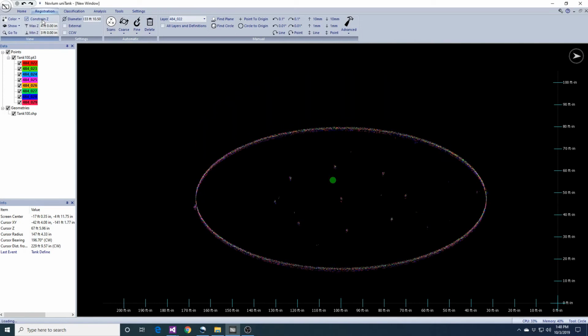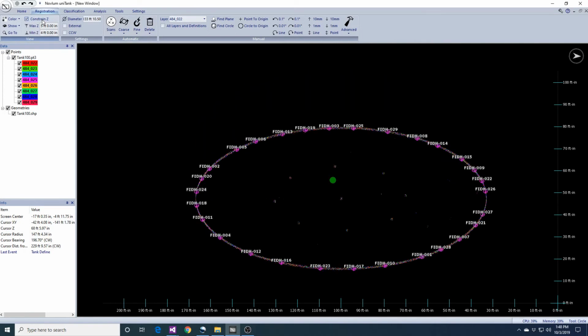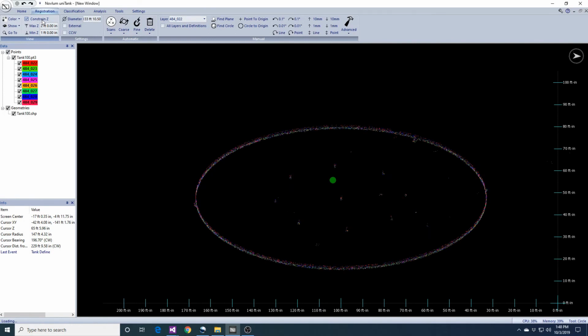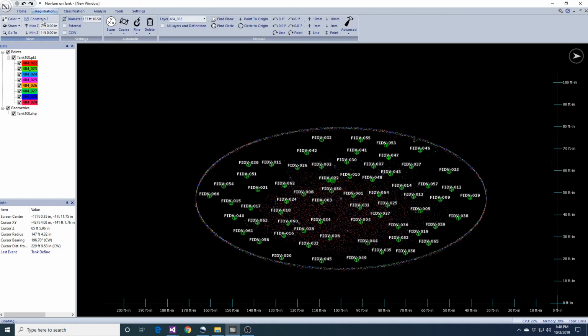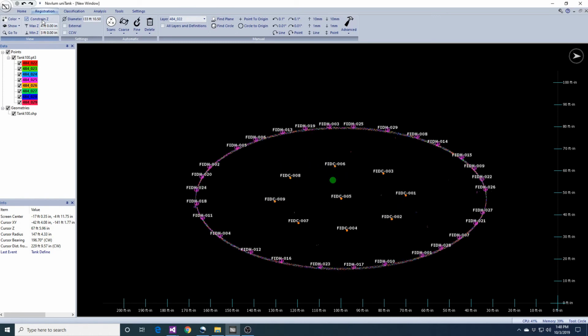The surface fiducials on the shell control horizontal translation. The surface fiducials on the floor control vertical translation. Finally, the column fiducials at each column control Z-axis rotation. We will discuss the topic of fine registration in more detail in subsequent videos.